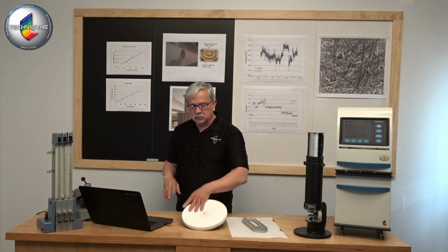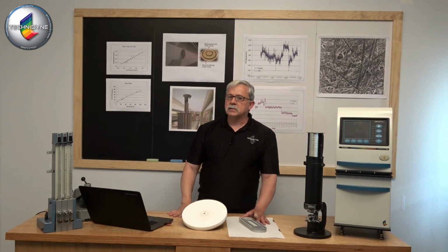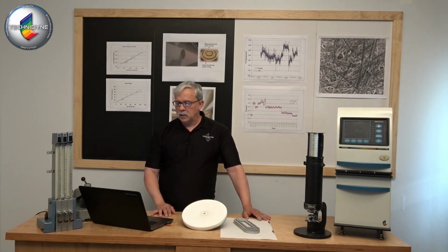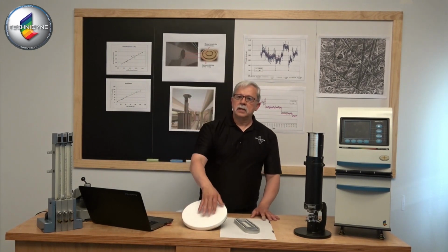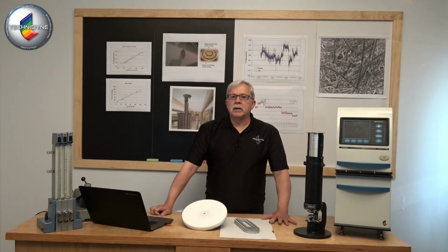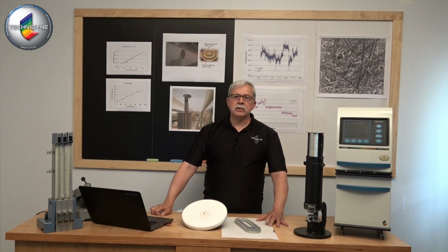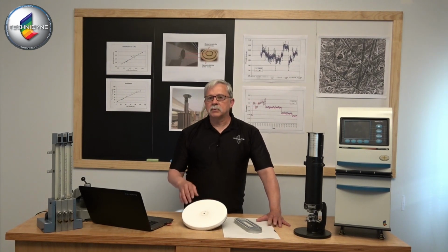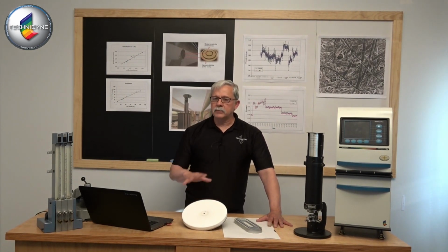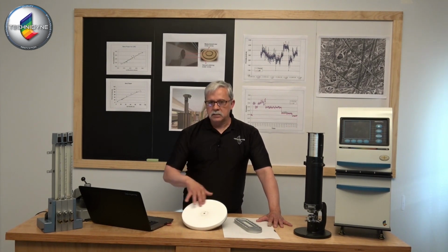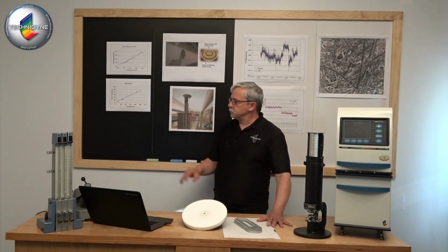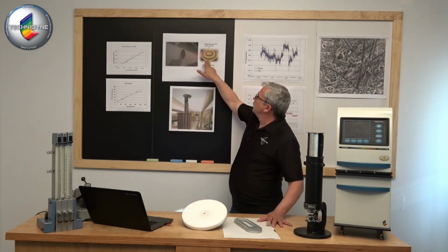This measurement head comes in contact with the web. The surface of these measurement heads is made of some very durable, low friction coatings, and we've experimented with a number of different types of coatings. Some are less susceptible to static. Some are less susceptible to scratching, to marring. All different types of designs of the measurement head, all different types of coatings for the measurement head.